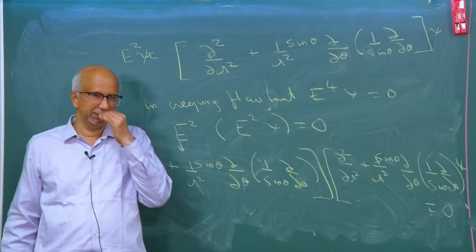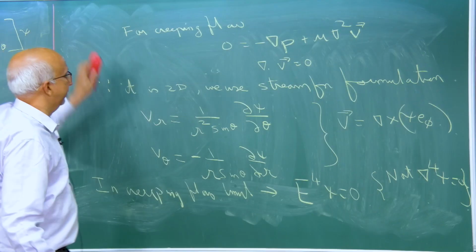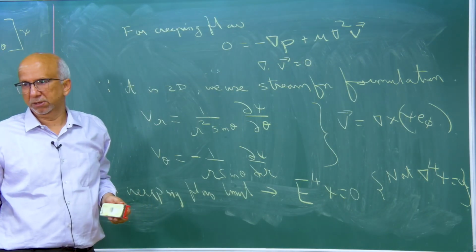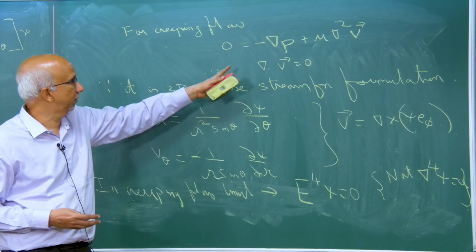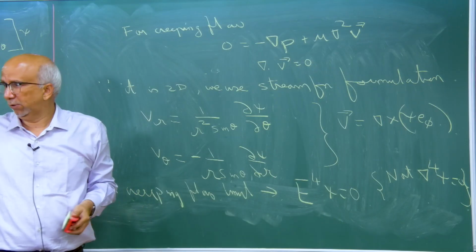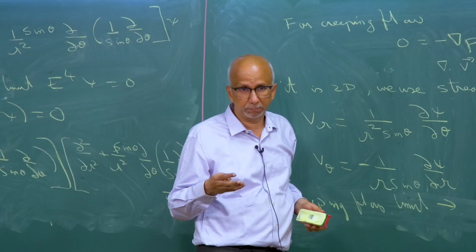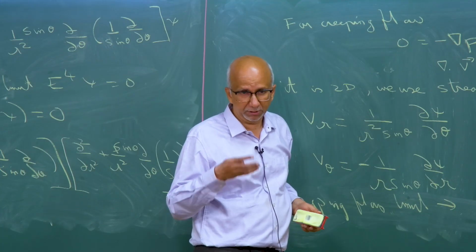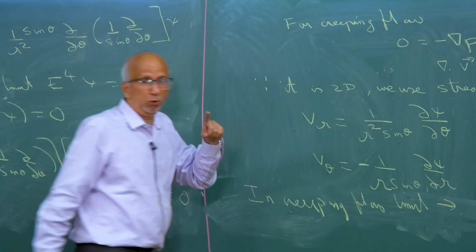Okay. So, this is the stream function which we have to solve for. The advantage, like I told you, is we have eliminated the pressure; this business of having to find pressure using continuity and all that is gone. I only have to solve for one equation. Only problem is now it is a higher order equation. It is a fourth order equation, not a second order equation.